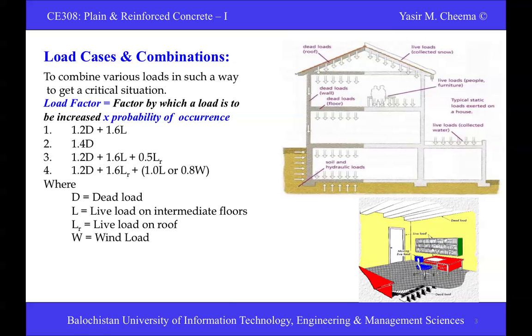The load of this table, or something hanging on the slab, is dead load. If this can move, it will not be considered as dead load. This one is fixed, so this is dead load. Something hanging with the walls, with the doors, is dead load. If a person is on some kind of slab or beam, it would not be a dead load. It would change with time.